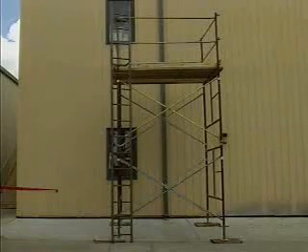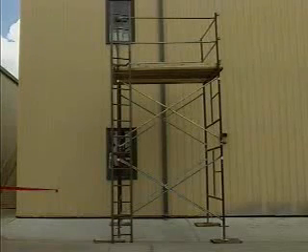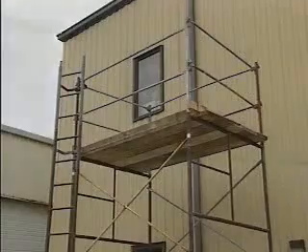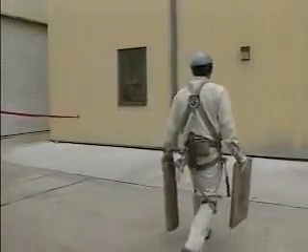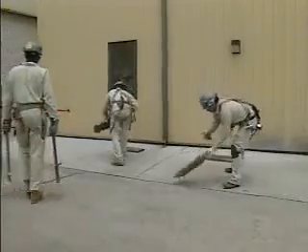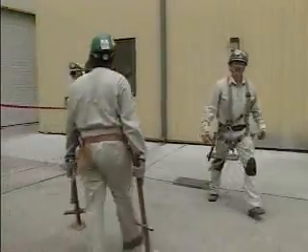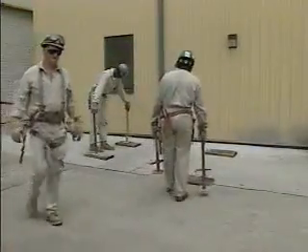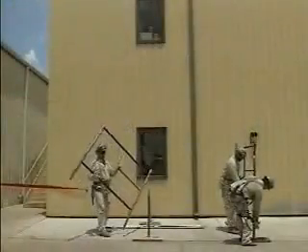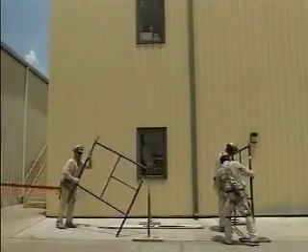Most of the remaining components are similar to those found on other types of fixed scaffolding. Many of the steps involved in erecting a tubular welded frame scaffold are similar to those used for other types of fixed scaffolds. For example, once it's been determined where and how high to build the scaffold, sills are placed on the ground where the scaffold legs will be positioned, and screw jacks with base plates are put on top of the sills. Then the vertical end frames are lowered onto the screw jacks.